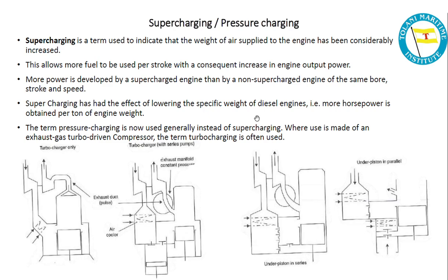So first of all, before going to turbocharger, we are going to see first what is a supercharger. Whenever we talk about supercharging, turbocharging basically comes under supercharging itself. This term indicates that the weight of air supplied to the engine has been considerably increased. This allows more fuel to be used per stroke with the consequent increase in engine output power. More power is developed by a supercharged engine than by a non-supercharged engine of the same bore, stroke and speed.